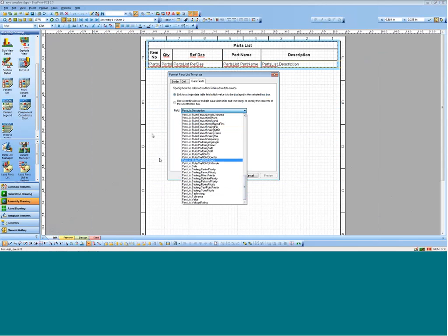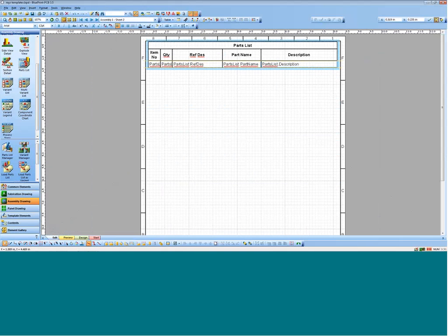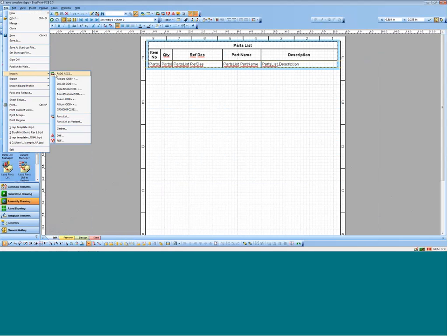And what you can do is actually import those into BluePrint. You simply import that parts list. You associate it to the one that's in the current design, usually by reference designator, part name, something like that, and it updates those parts with that information. And then all that information is available to you to drop down onto a drawing in a parts list or view or so forth.